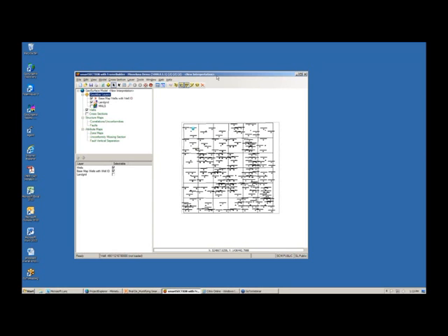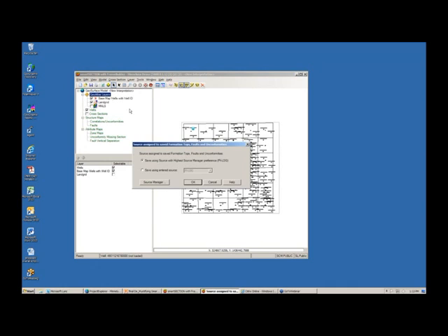After you select your layer and your filters, the next step is it's really important to define your preferred sources, the source of the information that you're going to use in your model. To do that, we're going to return to Edit, but this time we're going to choose Saved Source. This box serves two purposes. It establishes which source is going to be used to display the tops in your cross-section, and more importantly, it establishes what source new tops are going to be associated with.